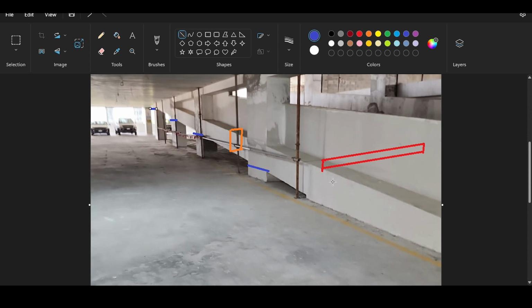And then you have to do the formwork of the beam. Now because the beam is inclined and straight, the formwork is not that dangerous, but you still have to set it out with surveying help. A quick winging it will never work. So stage one is basically to cast your concrete columns, those dudes. This is stage one in the construction. This is really a tedious and daunting, time-consuming task.